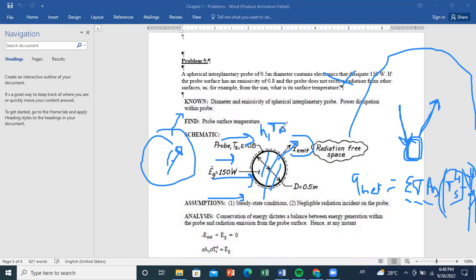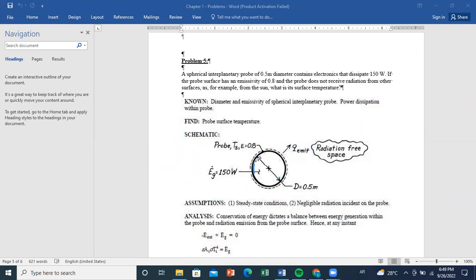all you have to do is a small energy balance over a thin layer of your system at the control surface of your system. Why? Because all processes will take place over the external surface. So if I take a small control volume embedding the surface, I can say that the generated flux will be transmitted by conductive effect to the surface, and then from the surface, this heat can get out through radiation and convection.